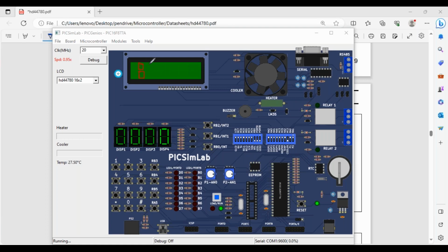If I use 5 cross 10 dots, I am going to occupy half of the second box also, like this. I can display only one character. I cannot display one more character here. In that case, I should use only one line. If I'm using 5 cross 10 dots for one character to be displayed, I can use only one line. So if I use 5 cross 8 dots, I can use 2 lines to have the data displayed. Are you getting this?